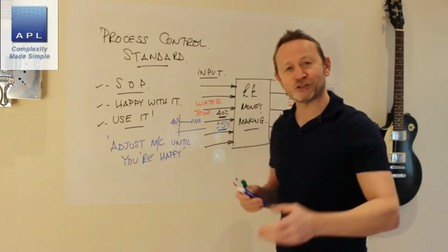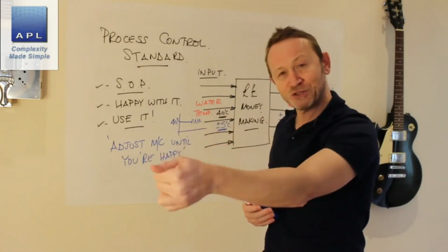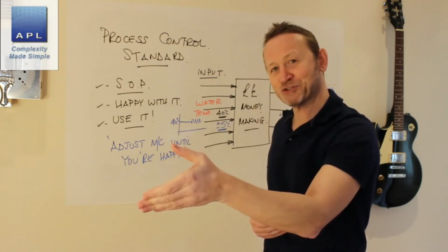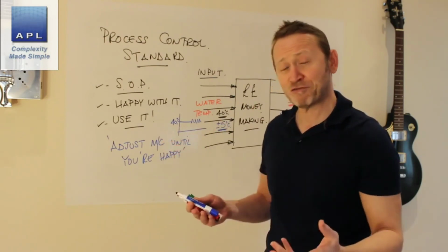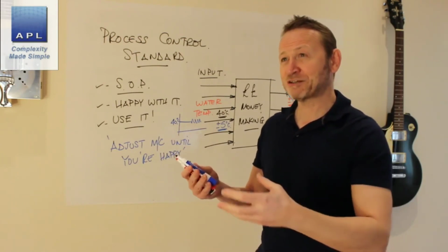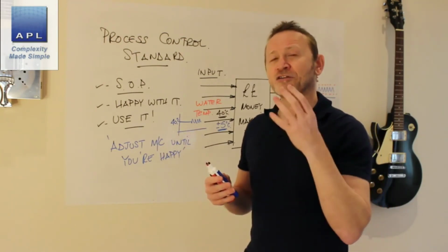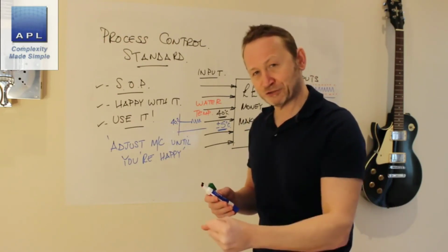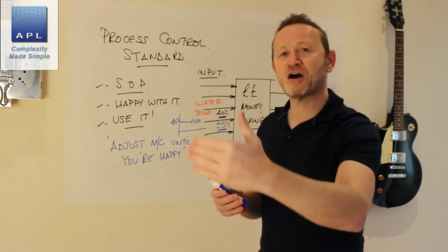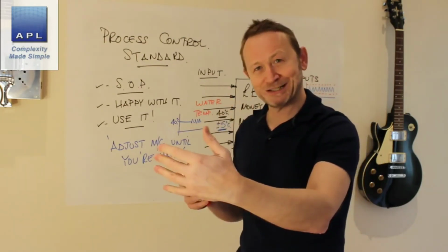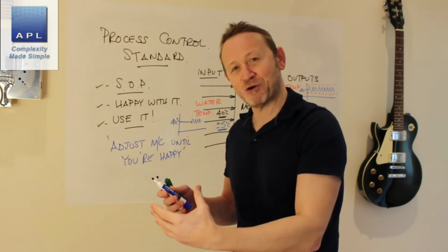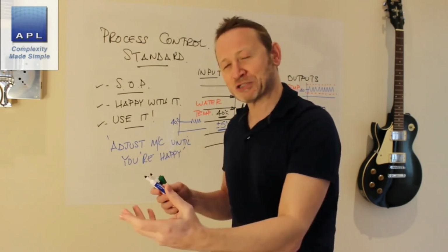Only give a tolerance if the item that you're looking at cannot hold in that position. So for example, if you said the filter, the flow through a filter, and you said, well, when we clean the filter out, we would like the flow to be at a particular level. And then you know that the flow will degrade to a point, then it's time to clean it again.